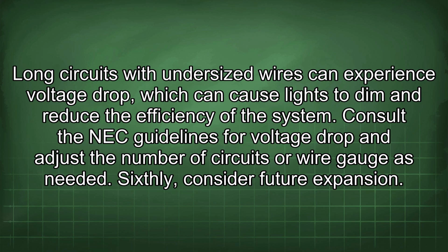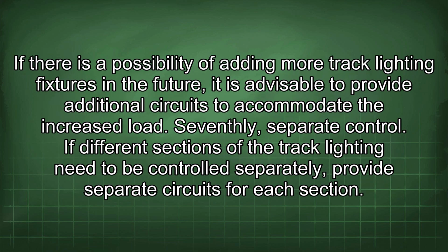Sixthly, consider future expansion. If there is a possibility of adding more track lighting fixtures in the future, it is advisable to provide additional circuits to accommodate the increased load.